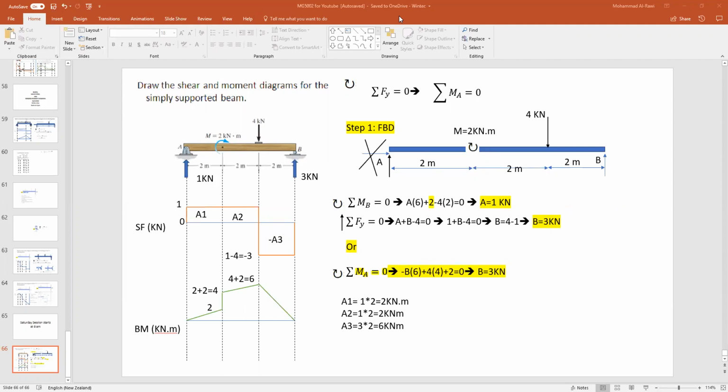Okay, why is the bending moment diagram positive, not negative? This is a really, really good question. Because if you look carefully, when I sketch the bending moment diagram, it's always related to the areas. I have 2 big areas in the positive direction. So those areas represent that the bending moment is positive. If I had A1 and A2 downwards, then everything would go down. So areas are the indication of where the bending moment diagram is going.